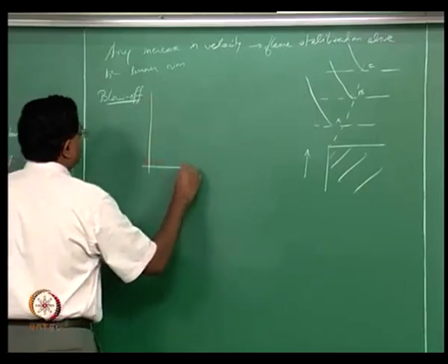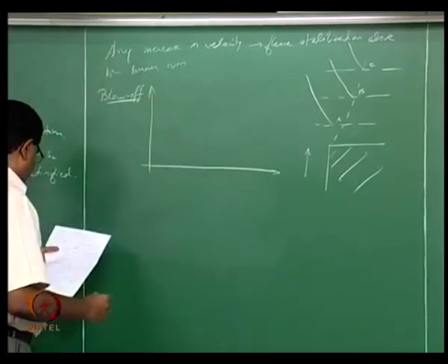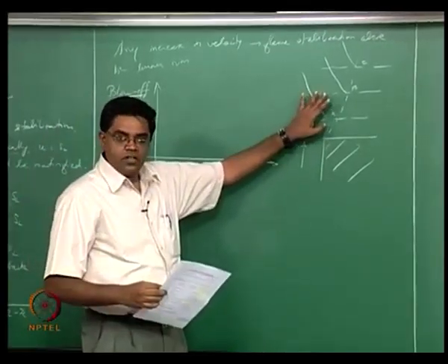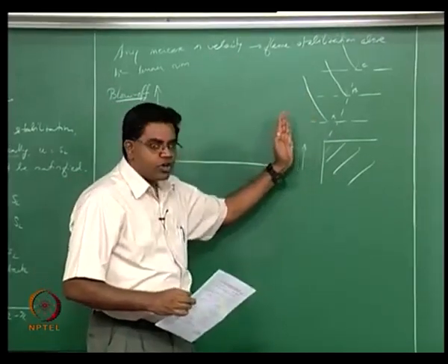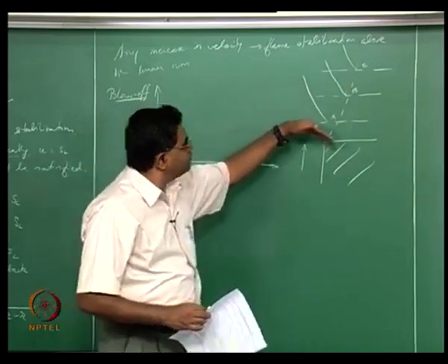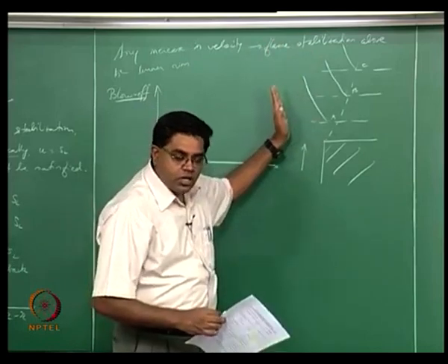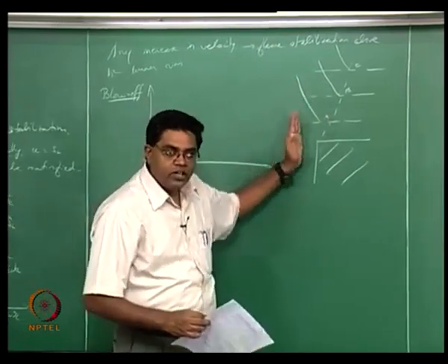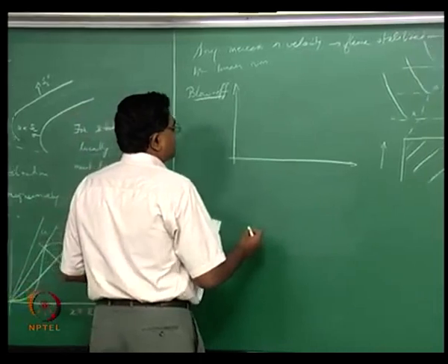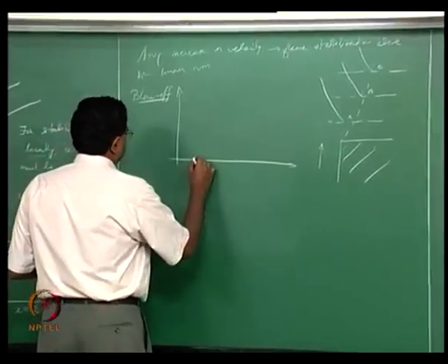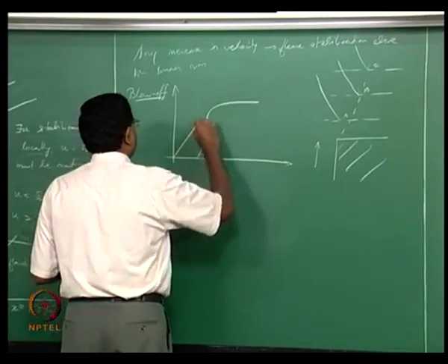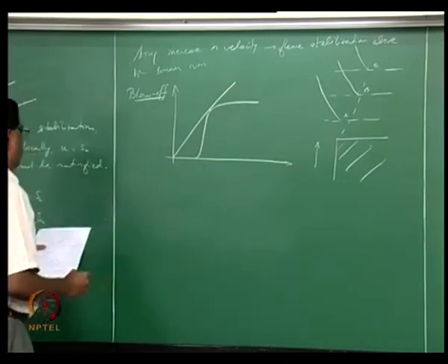The way the adjustment happens is, at a lower location you have intense heat loss. So the flame edge is more towards the center when compared to the other way. When you have less heat loss and a further location, the flame can be prevalent more closer to the rim radially when compared to if it is much closer to the rim axially. Therefore, for condition A, your SL is 0 for quite a while and then increases, and then you have a flame stabilization condition that matches this.